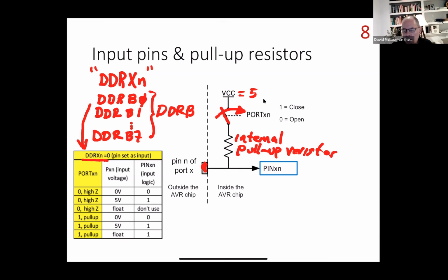Okay, I've got a question. What's the resistance of the pull-up? It's typically around 10 kilo-ohms. I think some reports actually show it as being 4.7 kilo-ohms. So it's around 5 to 10 kilo-ohms. And why is that? Why is it 5 to 10 kilo-ohms, and why isn't it a smaller value?